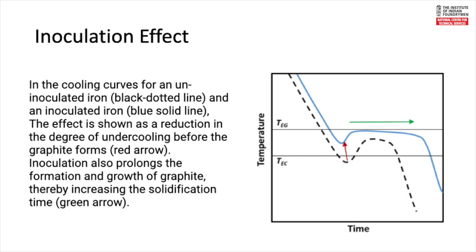So if you provide an adequate number of nuclei through inoculation, we are externally adding something into the bath which reduces the necessity for this thermodynamics driven phenomenon called undercooling to take place, because a surface is already available.